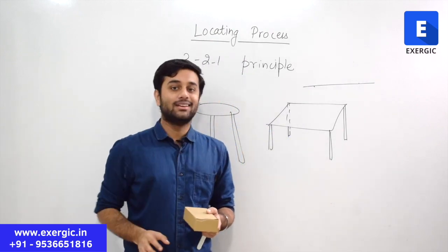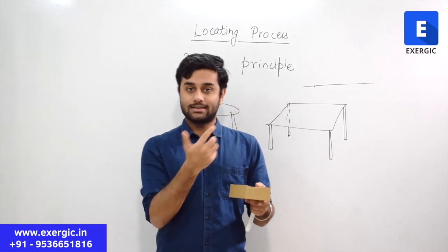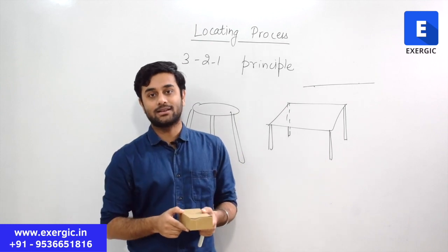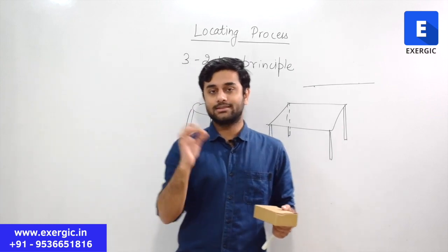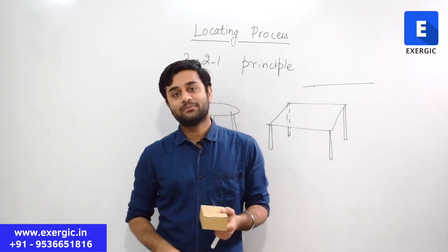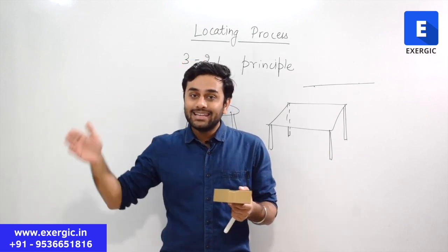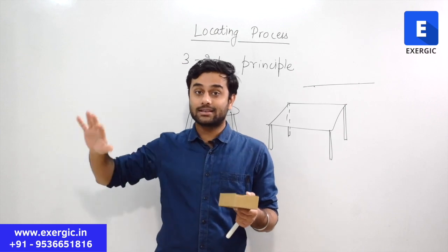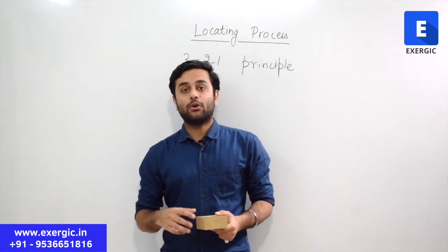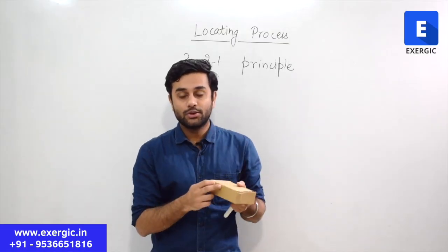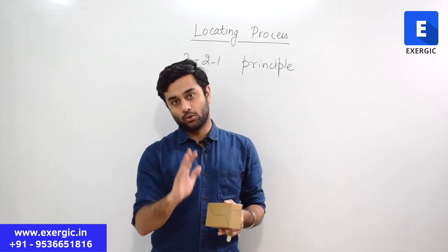This is the beauty of 3 legs in any discussion that we do in manufacturing. This is a limited application. In manufacturing, at a number of places, this thing is realized. 3 supports are extensively used to ensure that any tolerance variation that we discussed in metrology is not going to affect our manufacturing process. Now, while providing different supports using pins, there are certain tips, certain rules that you should follow.